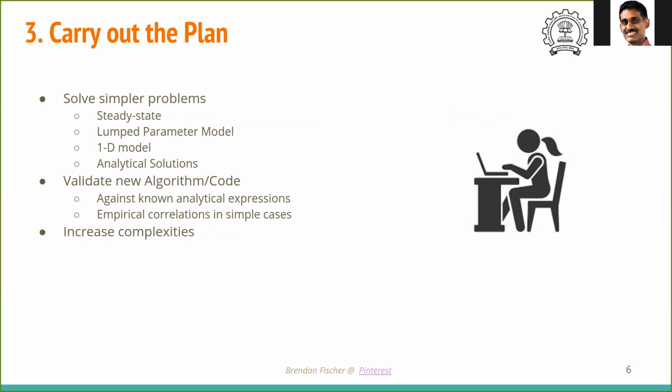Then comes the next level of higher complexity, what's called a one-dimensional model. Instead of lumping, saying that the entire change is 70 degrees, it changes from 100 to 30 along a straight line, not in a three-dimensional way, but along a line. That way you slowly make some simplifications and solve them, and look for analytical solutions.